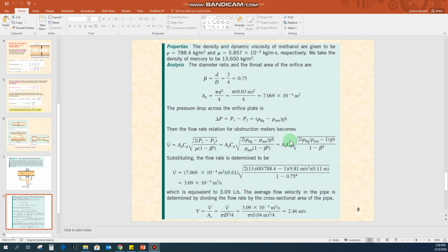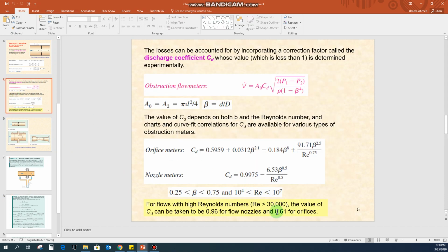Here you can also see that the discharge coefficient for the orifice meter is 0.61. This is the literature value that we get from here for the orifice, keeping these two conditions satisfied. But the value for the flow measuring device can change slightly when we change vendors.